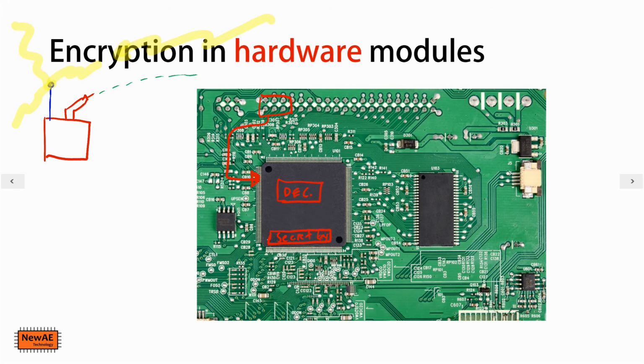So even if an attacker sends messages, it's never going to work. So it'll decrypt the received messages. It could do some further validation of them. So you look to make sure it was decrypted properly and that whoever sent it knows the secret key. And if so, maybe it sends a signal out somewhere to switch on the water. So this is a fairly typical embedded hardware task that might use encryption.